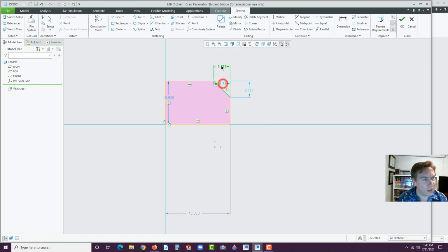Okay. Now here's the interesting thing: I have this dimension, this corner to the bottom edge, so it's not a typical chamfer. I mean, it is a chamfer essentially, but for some reason it was decided to do it that way. So what you could do is just dimension this to override that dimension. Go 6 inches. And now it's like this to this, and right in this window here, middle click, and that's going to be 51. And then let's fix this one. And we'll lock it.